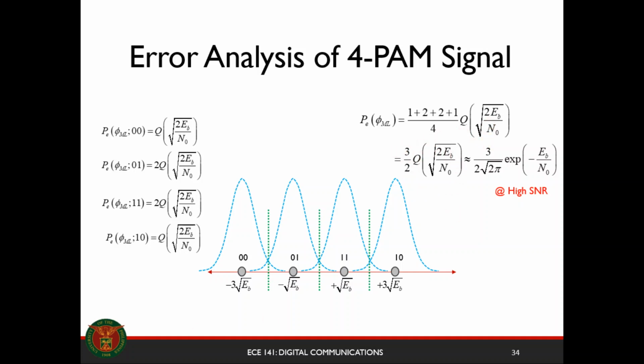So just notice, for your 4PAM, if you recall, the minimum distance is actually the square root of 2 times your energy per bit.